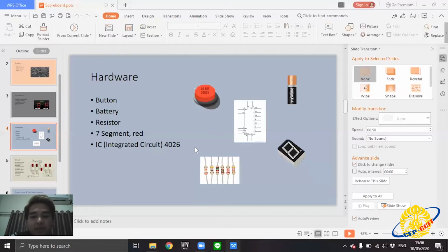And then we have 7 segments. The 7 segment displays are the oldest yet one of the most efficient types of display used in embedded applications. This display has nothing more than 8 LEDs inside it. These 8 LEDs are separated into segments, which can be named A, B, C, D, E, F, G. As shown,